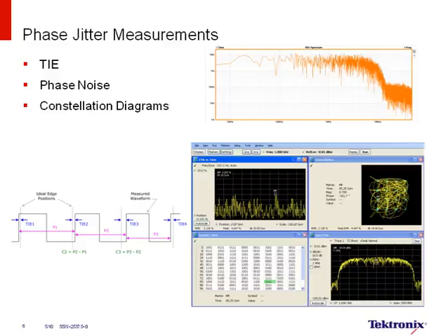The next question here is, can you accurately calculate BER from TJ measured at the output of the transmitter PHY? Or conversely, for a target BER, like 0 errors over 3 days for a particular high-speed PHY, like 8 gig Fibre Channel, can you determine what the TJ must be at the transmitter output of the PHY?